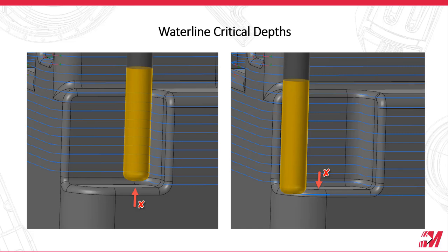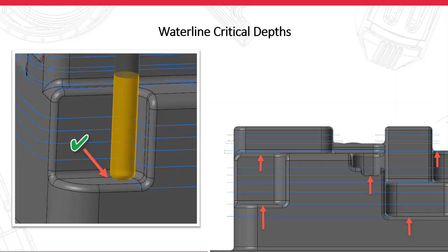So Waterline's critical depths. Waterline is a great tool path on steep walls, as we know. One limitation there was, depending on our depth cuts, if there was a flat there, it really didn't get closer, it was under that. So as you can see on the picture there, we had one or the other that we really couldn't control too well. So we usually had to come back and do some additional work there to clean them up.